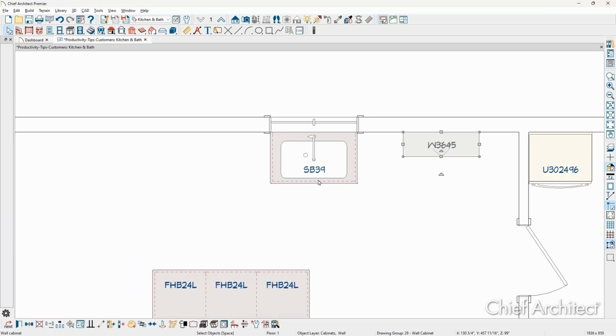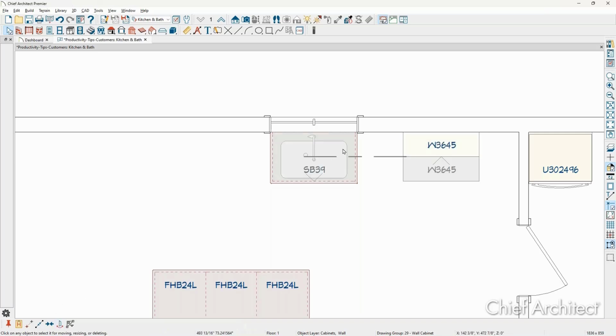Select this wall cabinet, copy, reflect around the window over to this side. So copy tool, reflect about, click, and that's a reflective copy around, and so the wall space would be exactly equal if you were to dimension those out. Awesome, thank you.